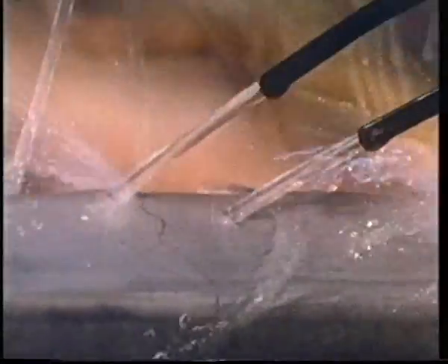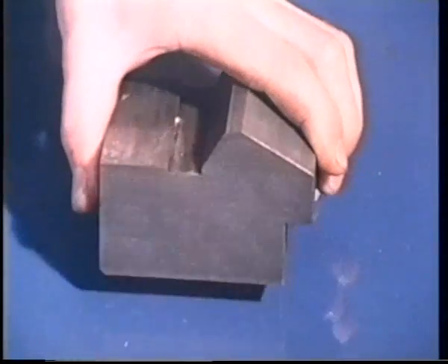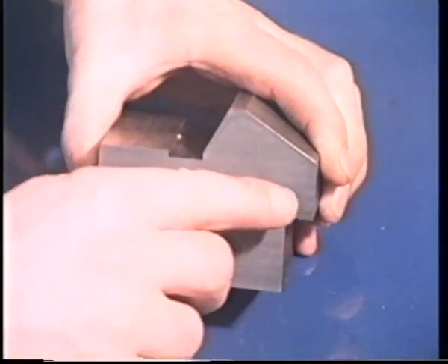The hot metal is then cooled rapidly with water. This heating, followed by rapid cooling, hardens this particular material. If we look at a specially prepared cross-section through the slideway, you can just see the hardened area around the edge.